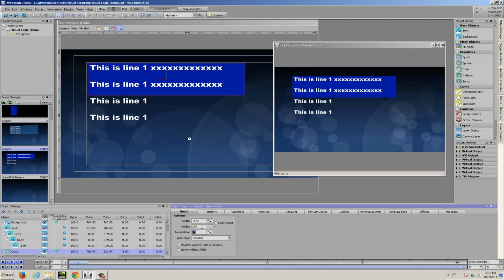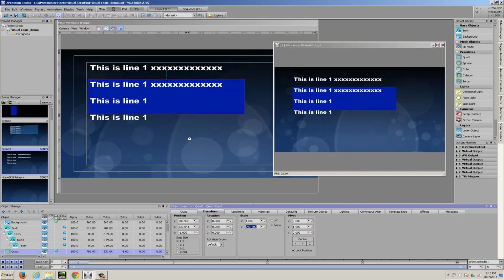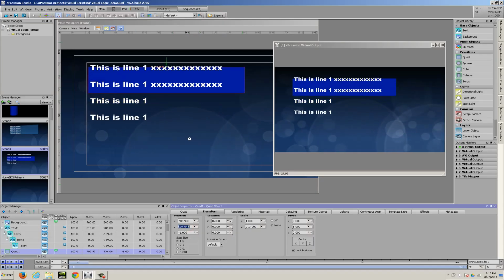So we're going to change the height of this quad to 1. We're also going to position the pivot point at +1 so that when I increase the scale, my object scales vertically in a downward direction. Because obviously my text objects, as I insert line breaks, are scaling in a descending fashion, and I want the quad to do the same thing. So we just want to make that one modification so that it scales from its top edge effectively.